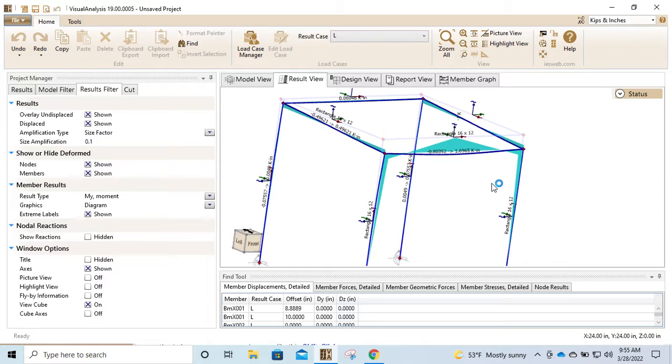Second part is calculate the global reactions at node 1 and 3 and indicate those on a sketch. It's obviously straightforward. Now using mechanics, plot the internal moment, shears, and axial forces in element 2. As we know, we don't have intra-element compatibility.